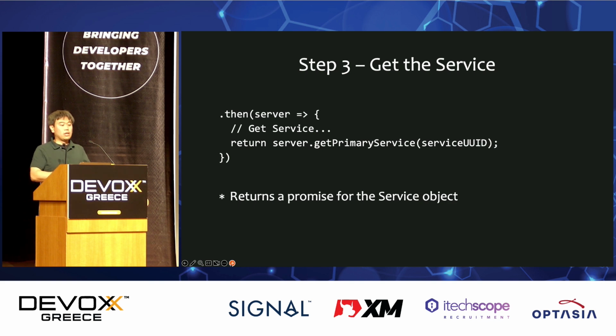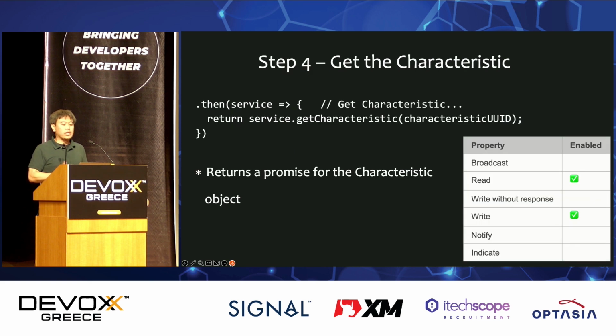So in order to do development into one of these Bluetooth devices, of course, there's the client side, which is the one we are building, or the web Bluetooth. But there's also the firmware side. That means the program that runs on the Bluetooth itself, right? So for example, if you're talking about a watch, and you're trying to connect Bluetooth on that watch, there is code that's running there that is the service itself. And then you have to know what services are available using the GATT profile, and what the characteristics are that are available. And then there's a specific identifier that you need to know in order to connect to it.